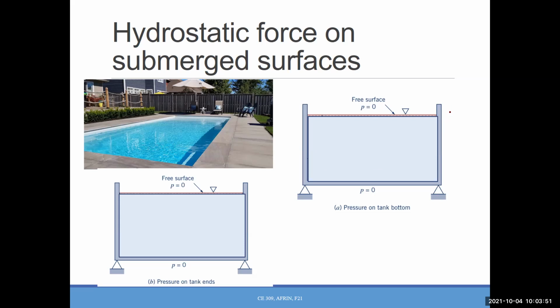So for a vertical plate and horizontal plate, let's draw the pressure distribution again. This is the water surface, so that is 0. And here, if I just use any arbitrary number, 3, 5 or something, if it's 3 feet, at this point, pressure is what? 3 gamma, right?